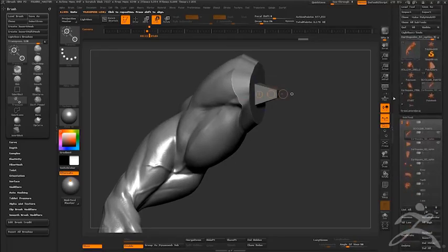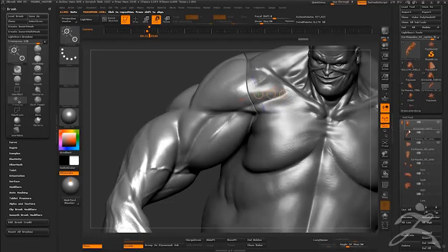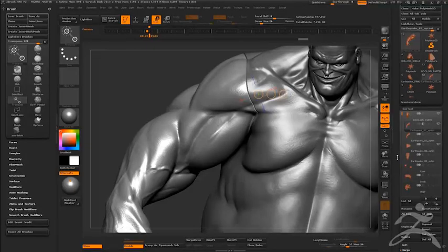So now I want to do the same thing with the body and the arm, only I want to create an object that's going to subtract this surface from my body. Okay? So what I'm going to do is I'm actually going to duplicate this arm. So I have my original, and I'm not going to hurt it at all. And I'm going to change this little widget right there. It looks like Pac-Man, something biting the wolf biting the moon, whatever your mythology is. That means that now this is set up to do a Boolean subtraction.